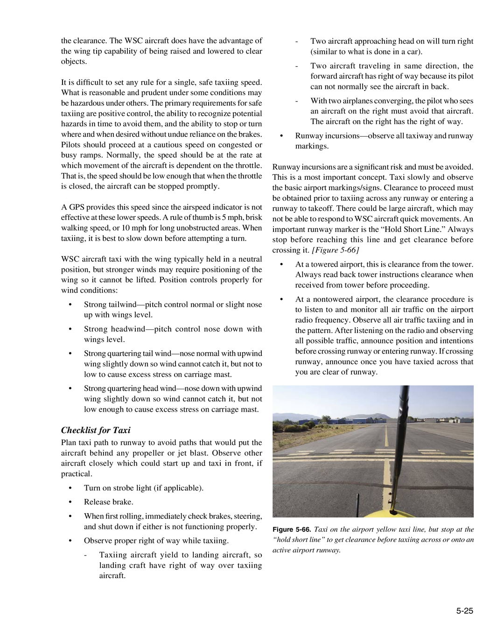WSC aircraft taxi with the wing typically held in a neutral position, but stronger winds may require positioning of the wing so it cannot be lifted. Position controls properly for wind conditions. Strong tailwind: pitch control normal or slight nose up with wings level. Strong headwind: pitch control nose down with wings level.